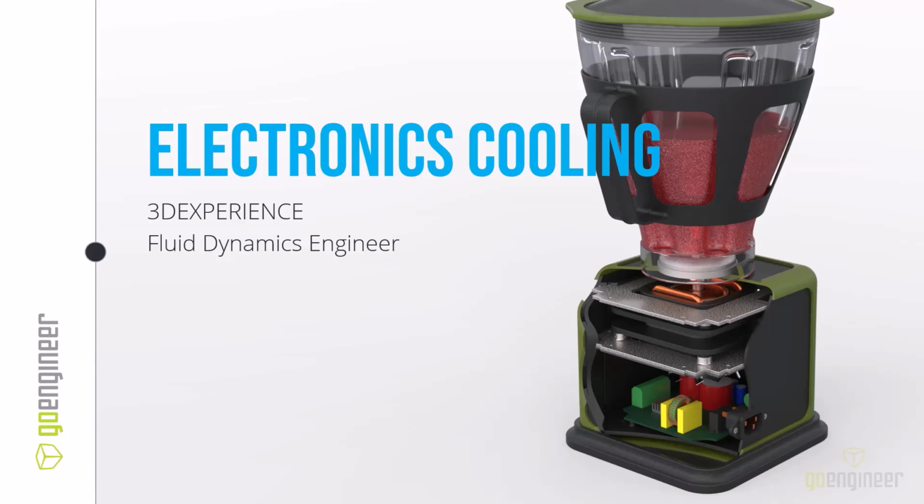Now, the blender has a motor controller board consisting of capacitors, controller chip, heat sink, transformer, and other electrical components. Due to the shape of the blender's base, the feet would need to be inset, causing stability issues. Now I used SOLIDWORKS Motion to kind of understand the tipping forces, and with those feet being inset, because it has to look like a cube, it just was going to have some problems. So we switched to an injection molded rubber mat, and that was designed to kind of elevate the pitcher and give it some stability with those tipping concerns. However, most blenders are open on the bottom so that air can move in and out through the bottom of the blender. This is going to block any vents that we will potentially have there.